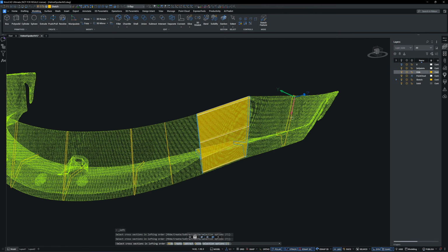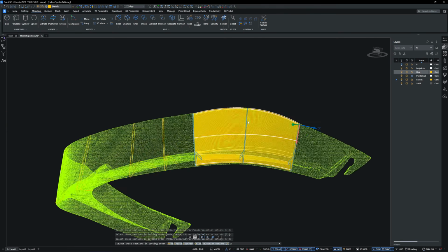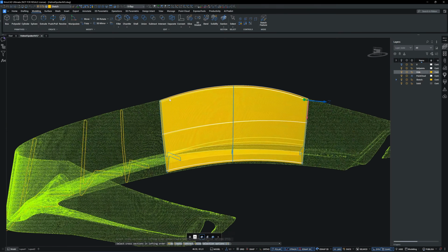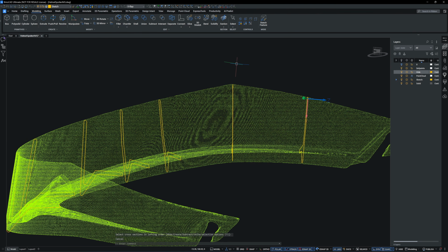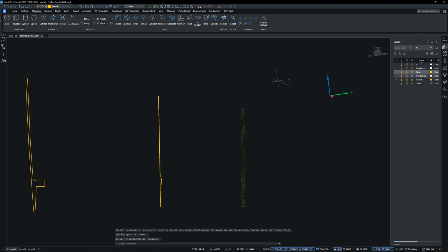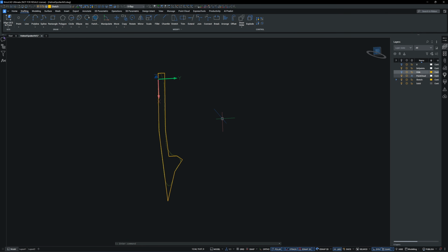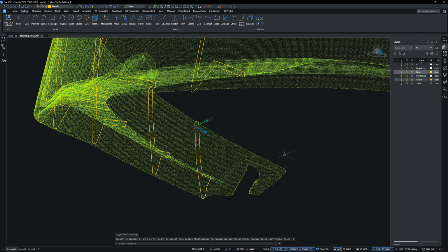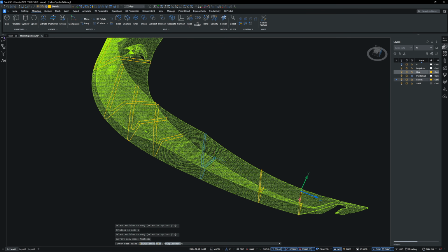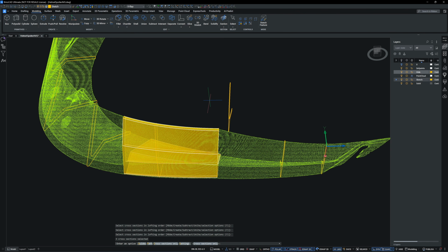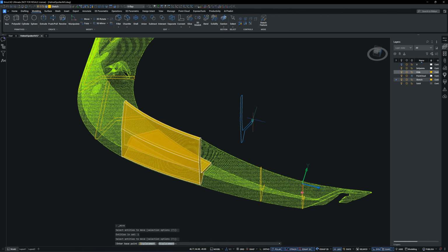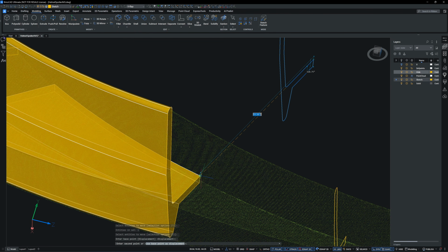I'm lofting 3 profiles over a sharp edge, but the result turns out rounded. When you encounter a sharp edge, you need to split the loft into 2 sections. Each section needs at least 3 sketch profiles to create a smooth, continuous loft body.